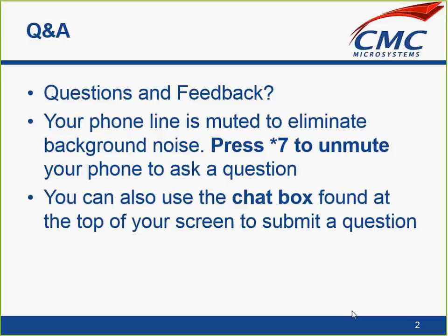One other thing, can I set the PNA-X IF bandwidth different from the NF bandwidth? Yes, both of those are different. The noise figure bandwidth is basically only dedicated to the noise receiver, and then the IF bandwidth for the S-parameters can be set separately, yes.